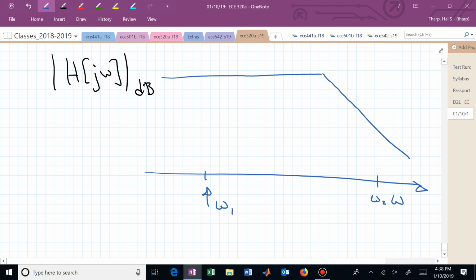That's Bode plots. And you'll learn how to do not only the magnitude, but the phase. And the phase tells you how it's shifted in time for different frequencies. You're going to be sketching two plots. When I say sketch the Bode plot, if I don't say do the magnitude or the phase, oh, I have to do both. You'll do the magnitude plot and the phase plot for the Bode plot.